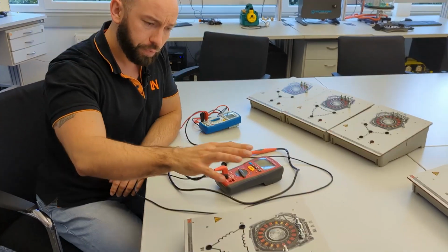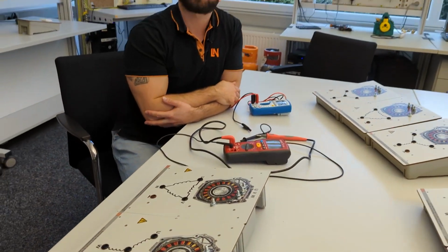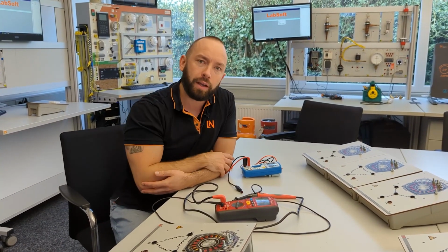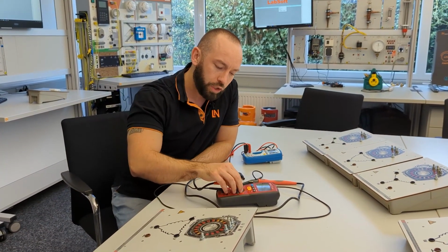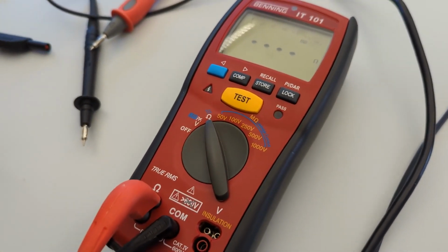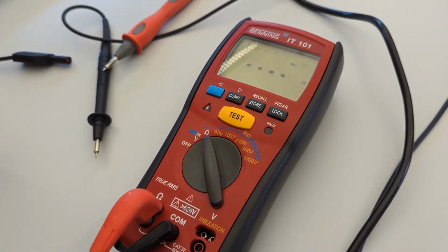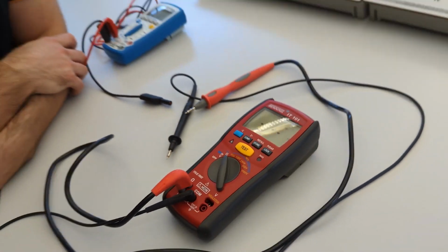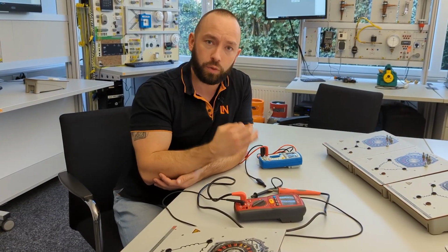But if we take a measurement on an electric motor, it's also interesting to measure the resistance of the coils. They are of course not in the mega ohm area, but in a very, very low ohm area. This is why we go to the normal ohm area in order to measure it. You just have to see how low your measuring tool can go. This depends on each individual measurement tool, so make sure that the tool can measure this low area of resistance.